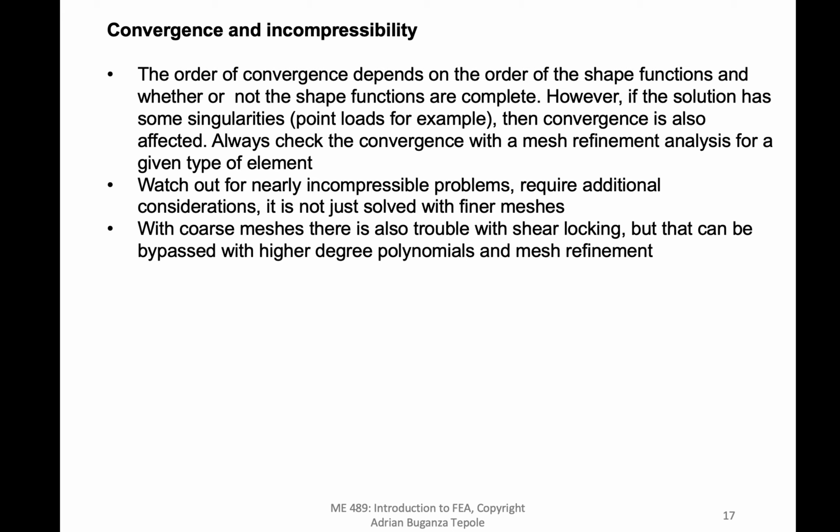So ideally, you would like to have smooth geometries, not point forces, and that would basically get you the best convergence out of your linear, quadratic, or cubic elements. So that's something to keep in mind. It's not just about mesh refinement, it's also about the regularity of your solution. So how smooth your problem is, whether or not it has singularities.